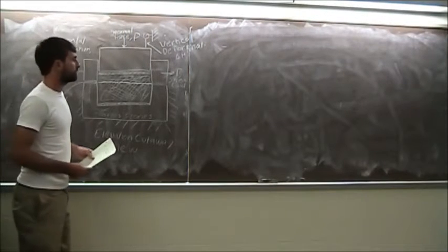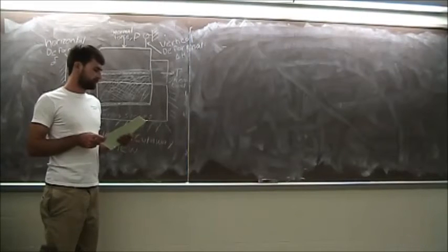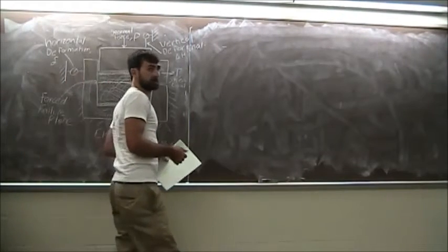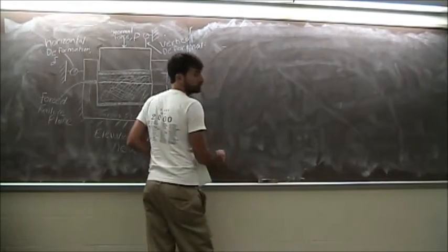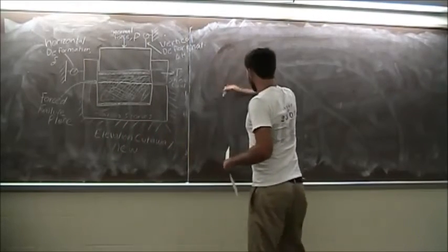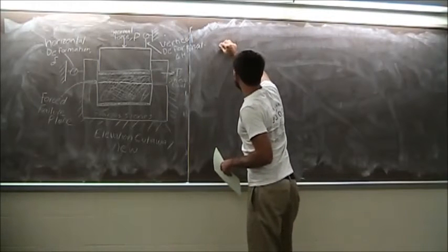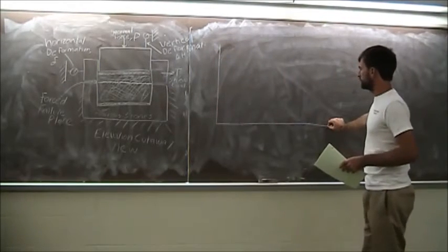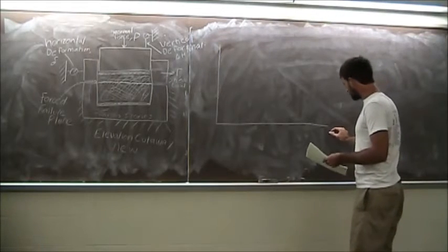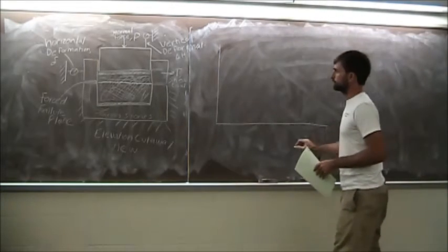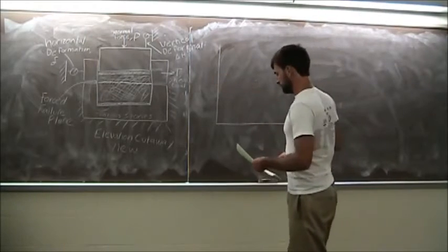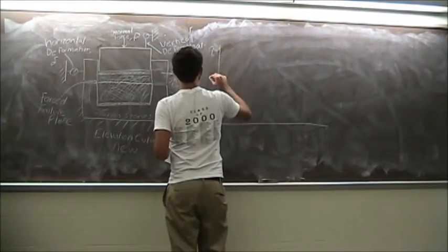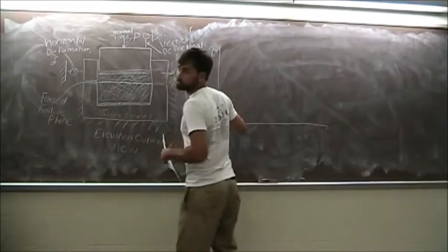Okay, I want to talk about what we're actually measuring when we're running these tests. We talked about the shear load, the horizontal deformation, and the vertical deformation. When you run these tests, you can plot up the results. We'll have delta here, which you remember is the horizontal deformation, and up here we'll have shear strength, or the shear stress.